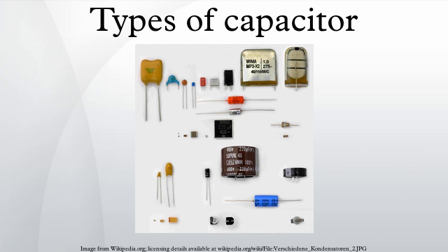Rleak is lower for electrolytics than for ceramic or film capacitors. The leakage current includes all weak imperfections of the dielectric caused by unwanted chemical processes and mechanical damage. It is also the DC current that can pass through the dielectric after applying a voltage. It depends on the interval without voltage applied, the thermic stress from soldering, on voltage applied, on temperature of the capacitor, and on measuring time.